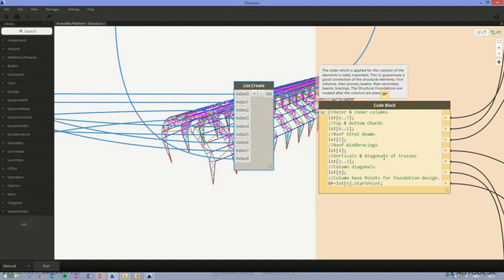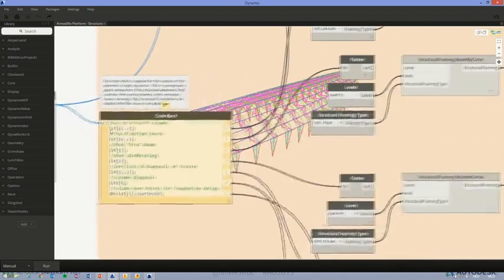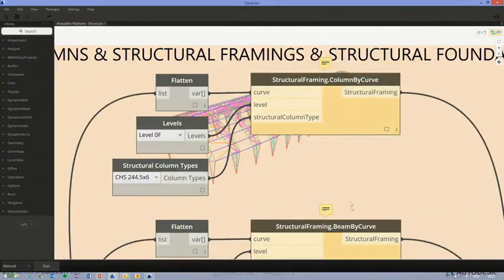So take that line, pull it onto a plane, which is the base plane of my structure, and you get these lines. We can call them grids. These are the column grids. And the end points of these lines will define the start position of each column, which will be this. The points create the lines.